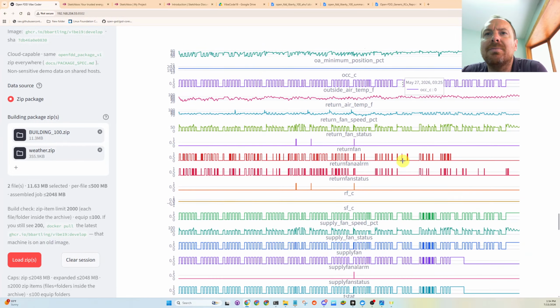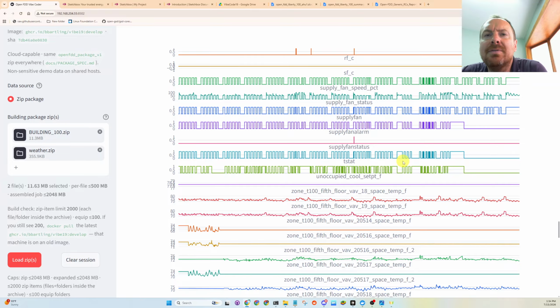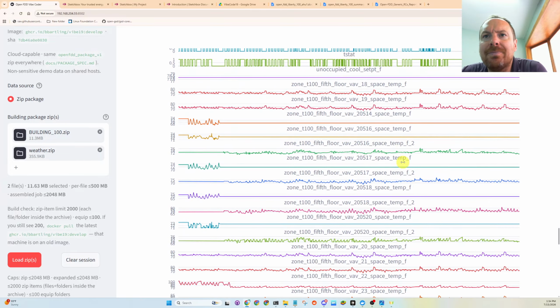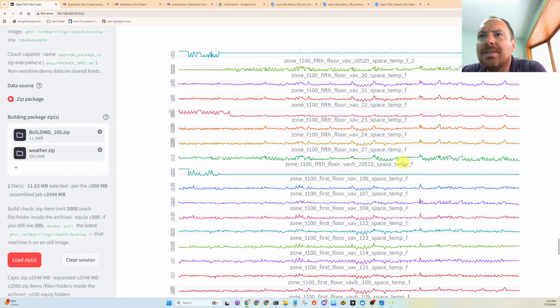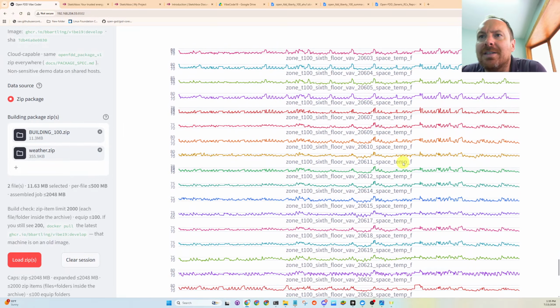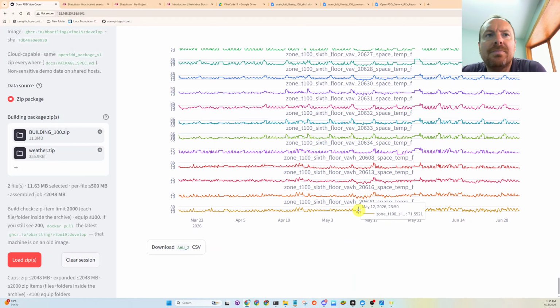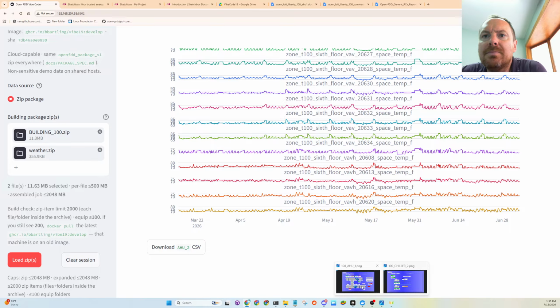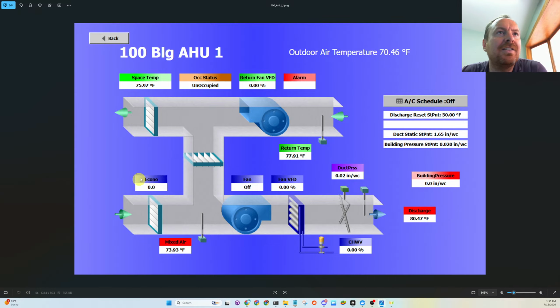Okay, so what I wanted to look at, what we were looking at yesterday, is this minimum position on the air handling units. So if there's one thing I can actually do today, it's validating that this is reading 100 on some of the charts I was looking at yesterday, which looks extremely unusual, but it's showing up as 0 here.